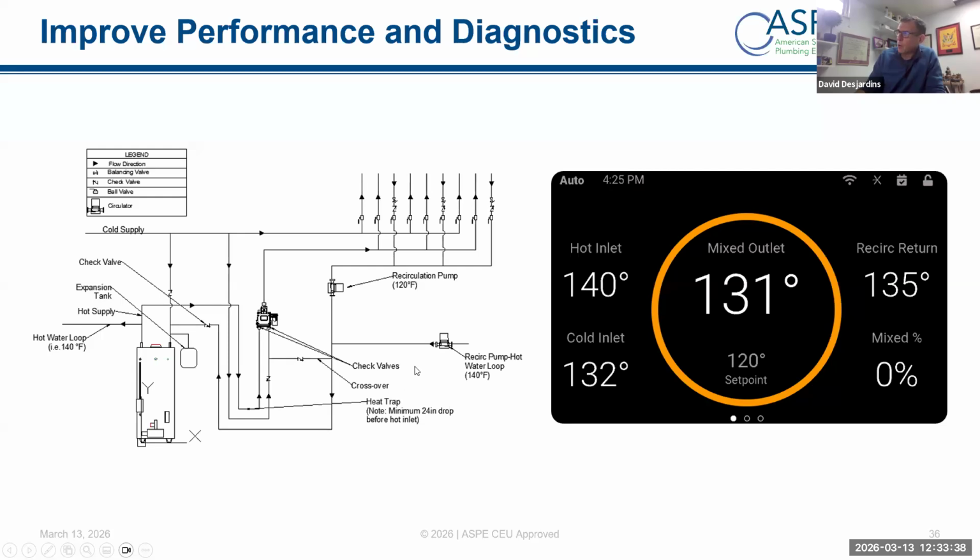And so the common question is, do you have a hot water recirc loop someplace in there? Here's an example of the piping. This is set 120, it comes back 120, but you notice over here, there's another pump. So I got this 140 loop that's going to feed the kitchen or laundry, let's say, and it's tied in before that crossover. You see that? That's unintended, obviously, but this is really useful in helping you dial in where to look. And I just asked, hey, do you have a hot water loop? Yeah, how do you know that? Where's it tied in? So we just got to shift that down. That's one of those things that I think is really valuable.